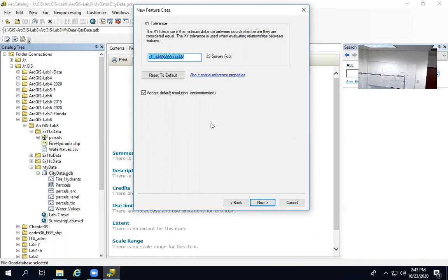In GIS, when we're drawing some stuff, let's say we're going to draw some points here. Put some fire hydrants or lines. If I put 2 lines so close together, the computer will add them as 1 line. This is called tolerance, which is similar to the accuracy that you had in surveying a few years ago. How many years do you have in surveying class?